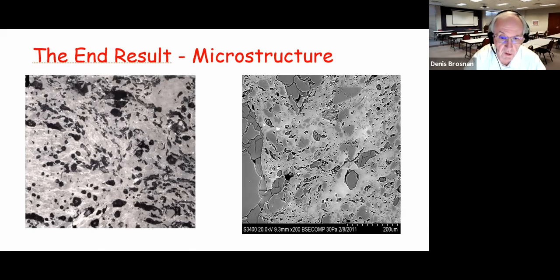Now there is a continuous phase in the brick. It's gray and white. The white is streaks of hematite, Fe2O3, so this is a red brick. The dark gray phase is the vitrified phase that contains the residual clay particles. All the clay particles don't form glass. In making a brick, they're there. We can't see them because they're so small.